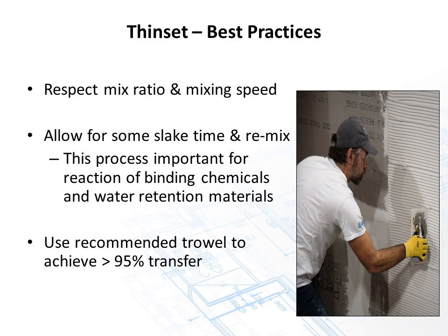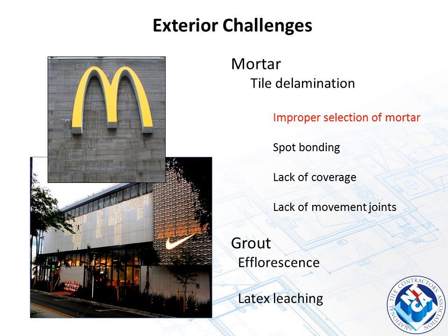So if we have voids back there behind the tile and or stone, and water can accumulate back there, it can freeze just like a water bottle freezes when you put it in a freezer, which means the water expands, pushing the tile away from the substrate, or unfortunately, typically breaking bond. Always try to achieve 95% coverage at a minimum. And check your coverage to make sure you're achieving that every once in a while.